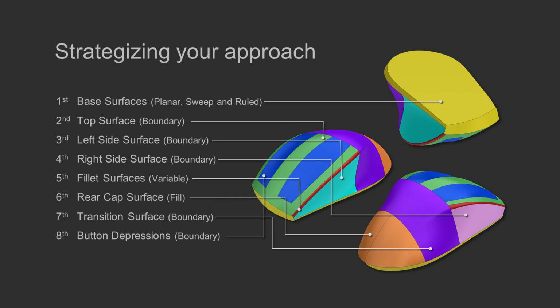It has really only one flat surface on it, and that's the base that I know of. So as you know, with SolidWorks and basic solid modeling, this kind of exercise is going to require that we do surfacing. And for any of you that have done surfacing, you know that it's generally an exercise of building up design intent through various patches that then come together as one complete form.